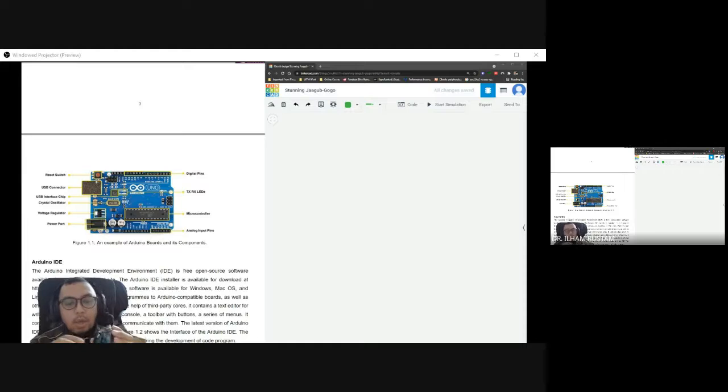That means if you have sensors to power up, a motor, and an LCD display, even though you only use 3 pins, 2 or 1 in analog and 2 in digital, chances are the motor won't turn because there isn't enough current, since it can only supply 1 milliamp. There are workarounds, of course, but that is advanced level, which you will learn later.